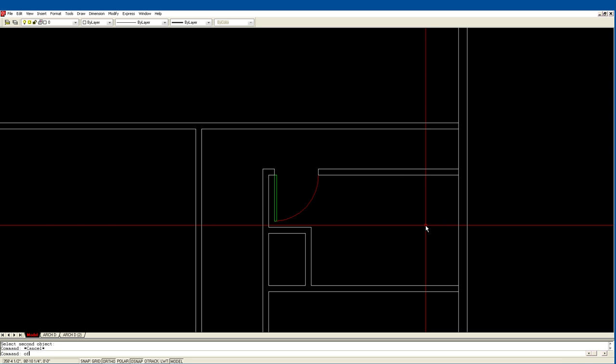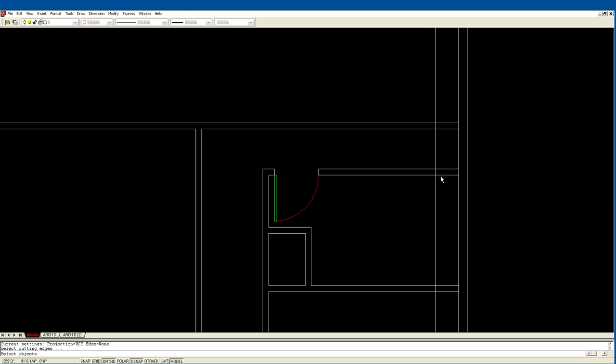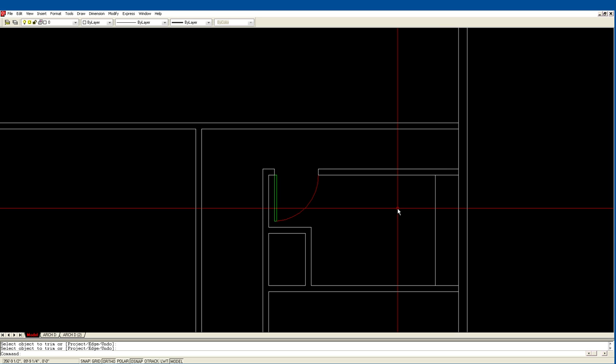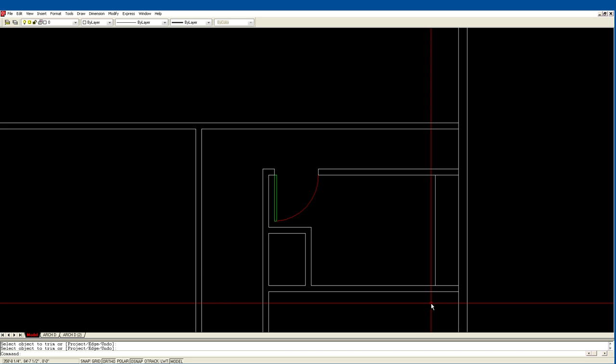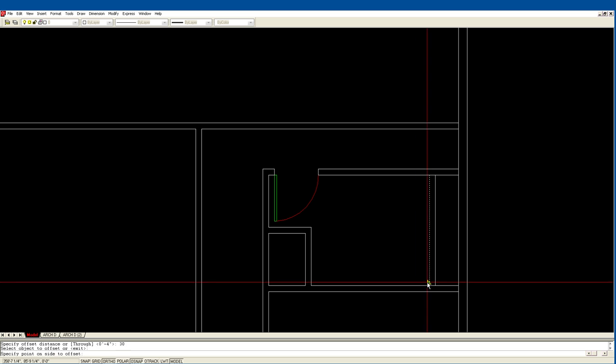Okay, let's offset 16. This is not a good setup. Offset 1.4, which is 16. Okay, from here. So that would be the shelf for that walk-in closet. Okay, and then he needs to put a door. Okay, well, let's do it. Let's offset 4 inches from that shelf, 30 inches for a door, 4 inches for clearance, and then 4 inches for a wall.